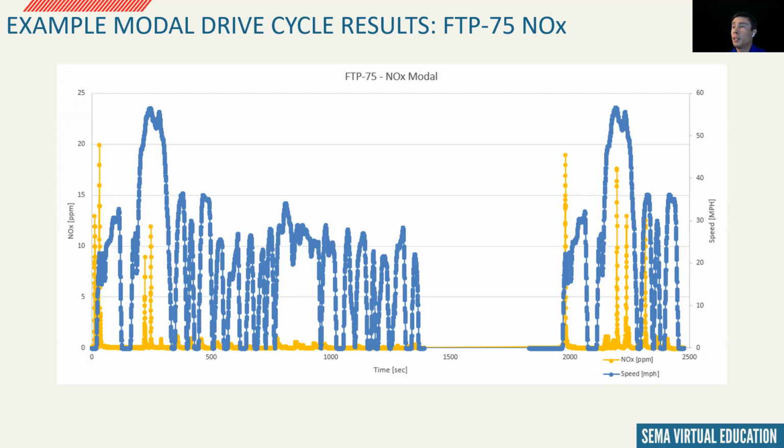These tables might use RPM and MAP as the axes, but could also have modifier tables that use manifold absolute pressure and engine coolant temp as well. Remember, we can play with the dithering here as well, spending more time rich if we have enough room in the hydrocarbons and CO to play with.